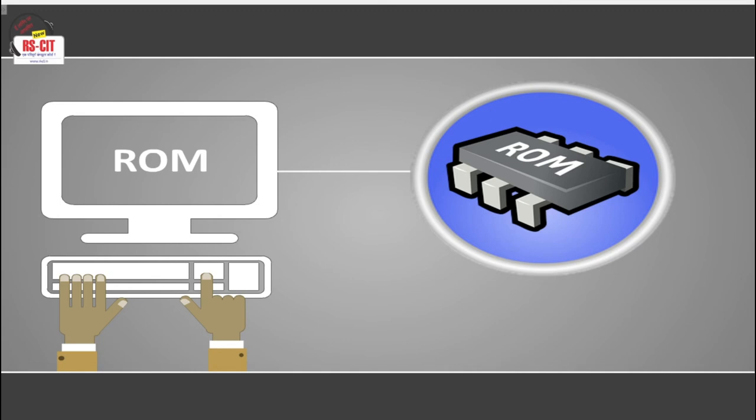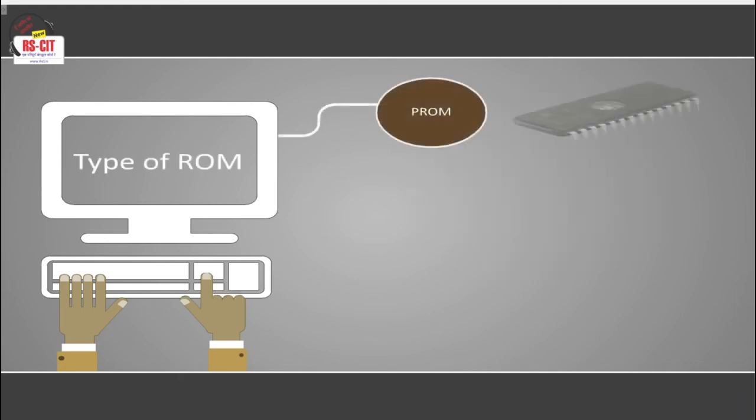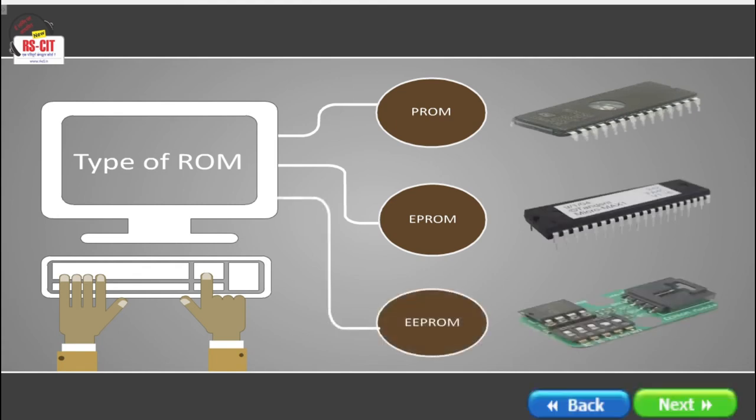Its content is created in the last masking stage of the chip manufacturing process, and it cannot be changed. Standalone ROM chips and ROM banks in microcontroller chips are used to hold control routines for myriad applications. ROMs were also widely used to hold the BIOS in early PCs as well as plug-in cartridges for video games. Types of ROM are PROM, EPROM, and EEPROM.